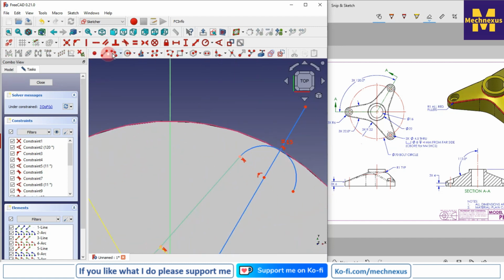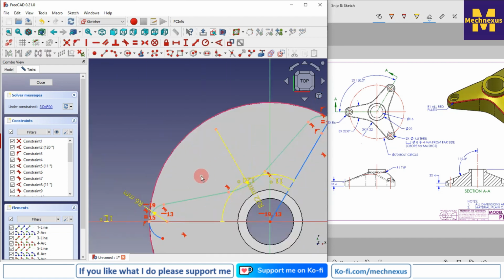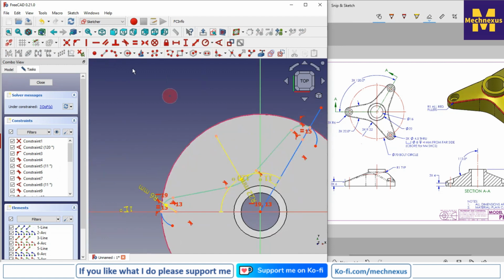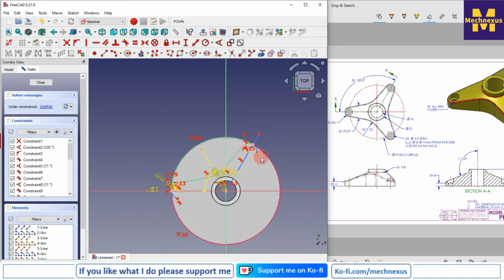Select the 3-point arc, make the coincident relation, and now this is the fully constrained. Now I will select the 3-point arc, join this and this point, and I will make it equal. So this is fully constrained.